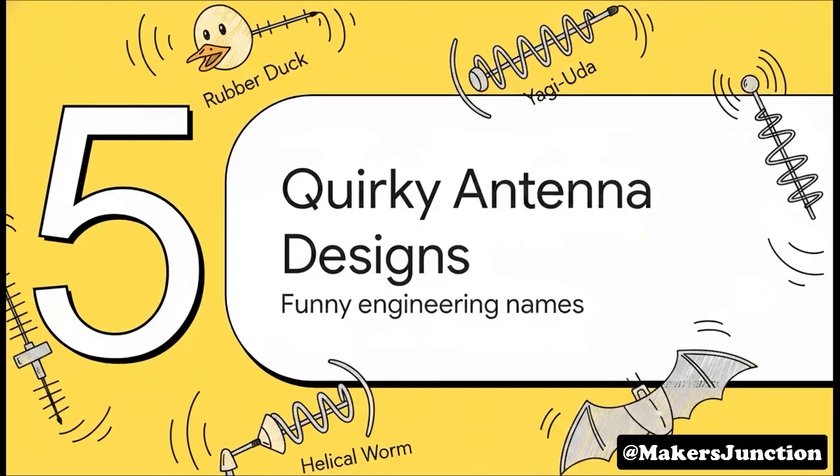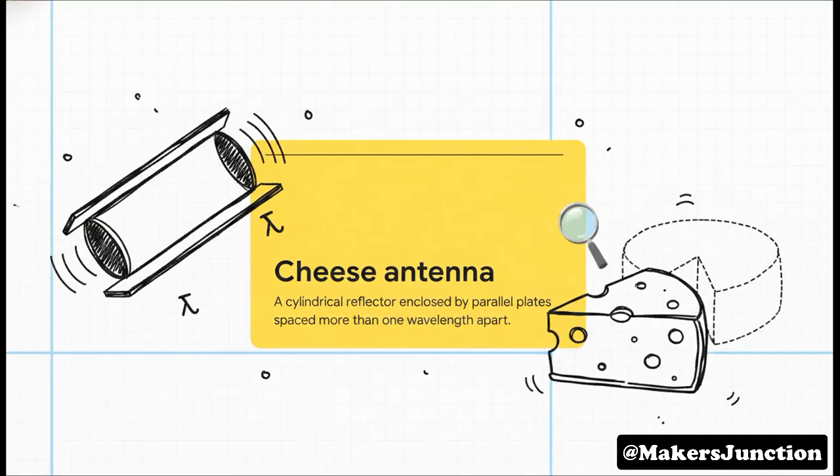And finally, Section 5, Quirky Antenna Designs, because engineers are actually pretty funny with naming things. First up, we've got the oddly named cheese antenna. According to the standard, this is a reflector antenna with a cylindrical reflector enclosed by two parallel conducting plates. But here is the absolutely crucial detail. Those parallel plates are spaced more than one wavelength apart. I guess someone looked at it and thought, yep, that looks exactly like a wheel of cheese cut in half.